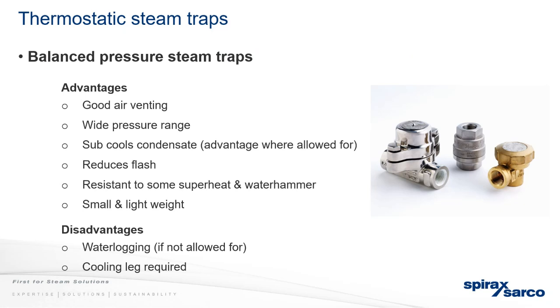The other advantage I will add to the thermostatic traps as well is because they're what we call free draining. So they always drain away. And they're perfect for things like pharmaceutical applications. So there's no condensate sat there where bacteria can grow.